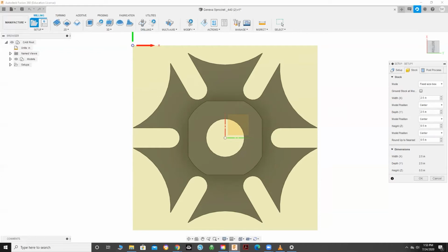The material measurements must be larger than the model itself. If your material is undersized, you will need another piece. Be sure your screen looks like mine, with the coordinate system in the top left corner and the arrows facing in the appropriate direction. Remember that your X direction is going to be your longest measurement.